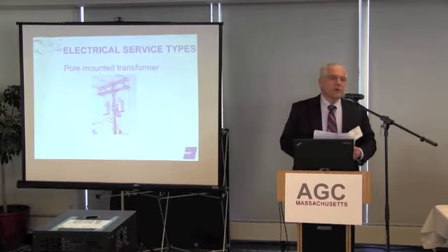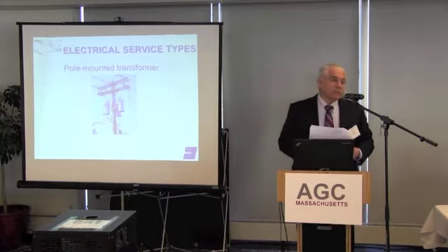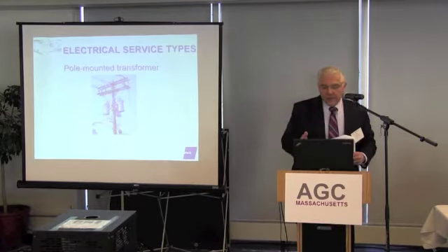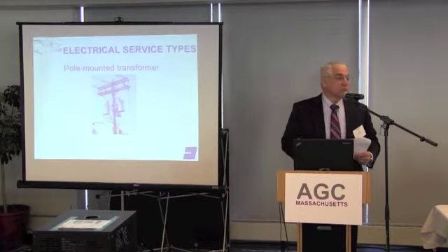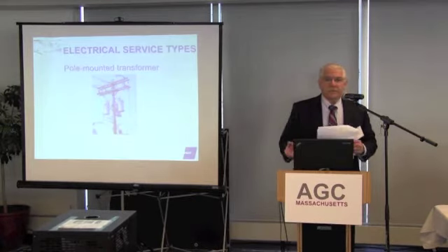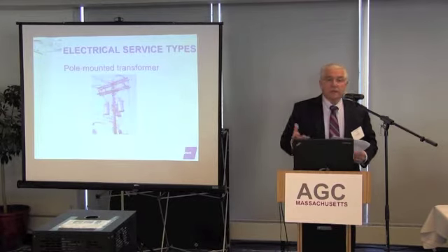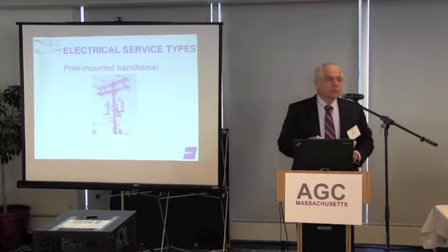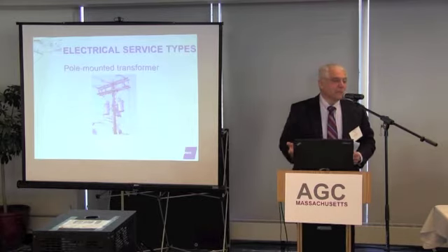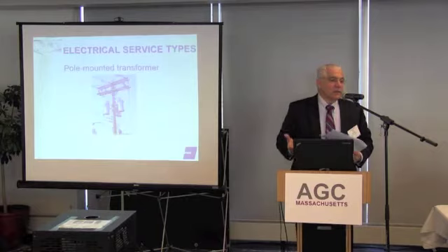Think of it as the high voltage in and the low voltage out, and that happens not only on the electrical service side, but also numerous times within the building when you're trying to transform voltage in the building, as Will said, for a commercial building or a building with a large mechanical load. A lot of those feeds would be 480 volts.